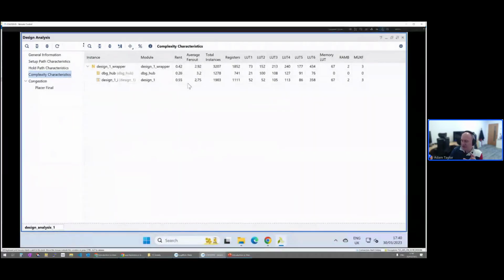One of the key elements of being a good FPGA engineer is not just throwing out VHDL or Verilog, but thinking about what that VHDL and Verilog is going to synthesize as, so you can control the fan outs and the amount of logic in between clocks, so you get better implementation performance on your device and spend less time cycling round trying to work out what the issue is.